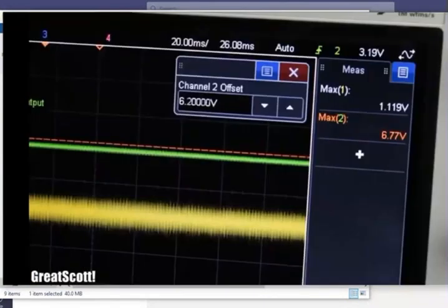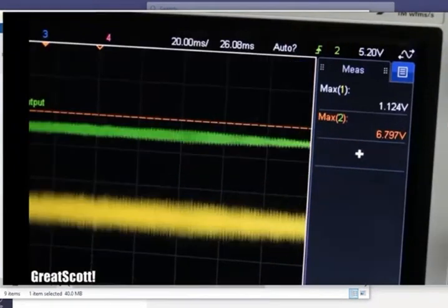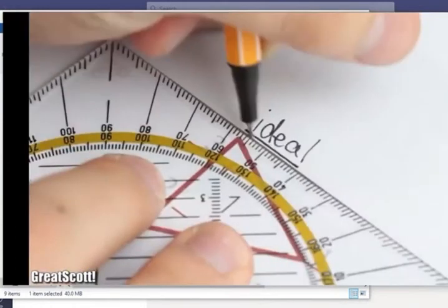This way the complete amplification does work to some extent, but because we are amplifying a DC voltage as well this time, we hit the 10.8 volt output limit of the op-amp pretty quickly. Why 10.8 volts instead of the 12 volts of the supply voltage? Well, there is no perfect op-amp.